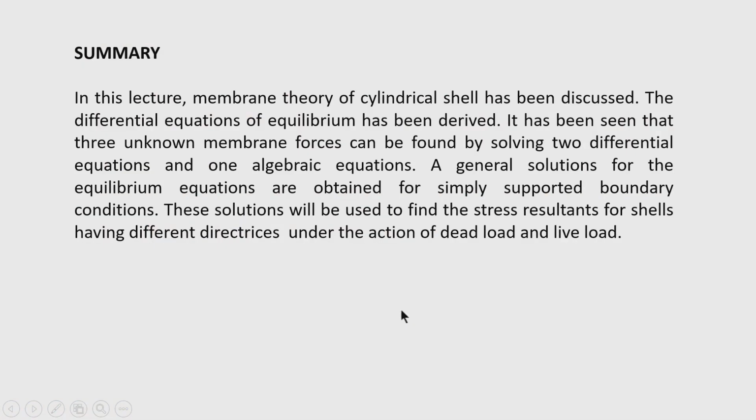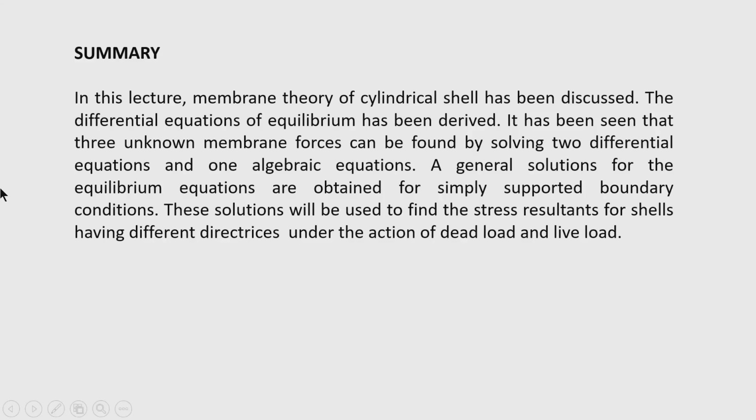So, today we have completed the derivation of the differential equations of equilibrium of a cylindrical shell using the membrane hypothesis. It has been seen that 3 unknown membrane forces exist in the differential equations, and there are 3 differential equations also. So, this problem is statically determinate, and we have attempted a general solution for the equilibrium equations for the simply supported boundary condition.